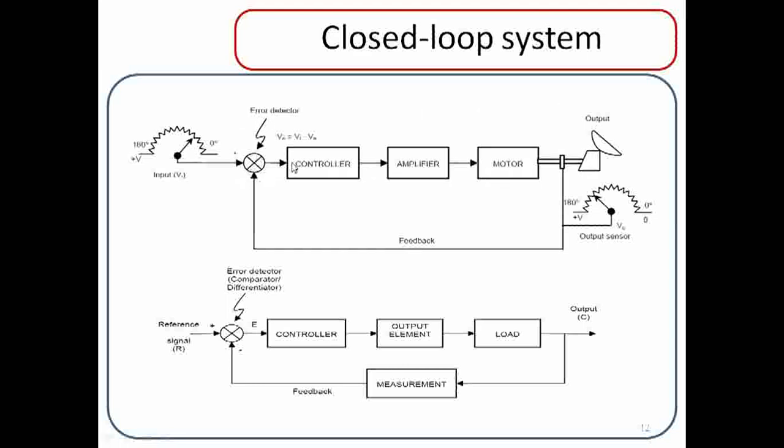Here the error signal exists, and the controller will give the signals to an amplifier, to amplify the electrical signals passed from the controller, and those electrical signals are necessary to actuate the motor at that particular capacity as per the input criteria.